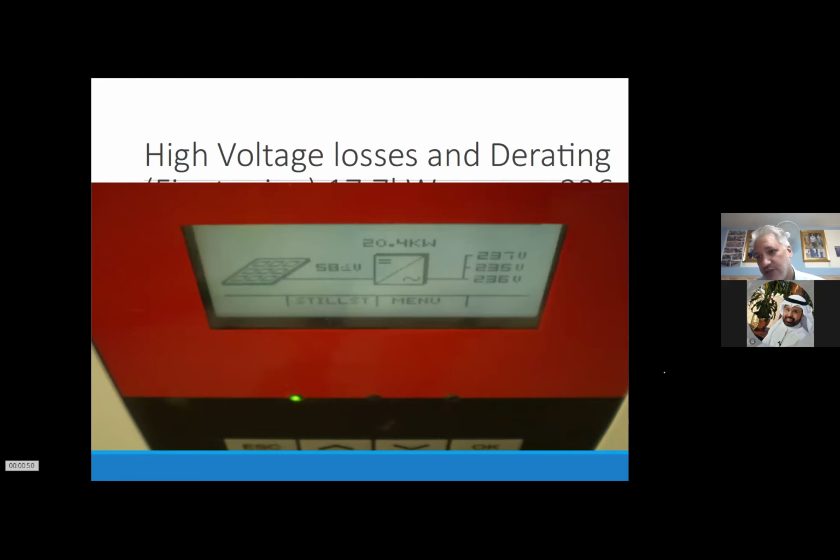It has to use some energy to overcome the long distance. And like I said, you can add cabling, so you can do like I did in Italy, because I could not change the tap setting. It was already on a different part on another plant. So I just added cable, so the impedance of the system goes down.